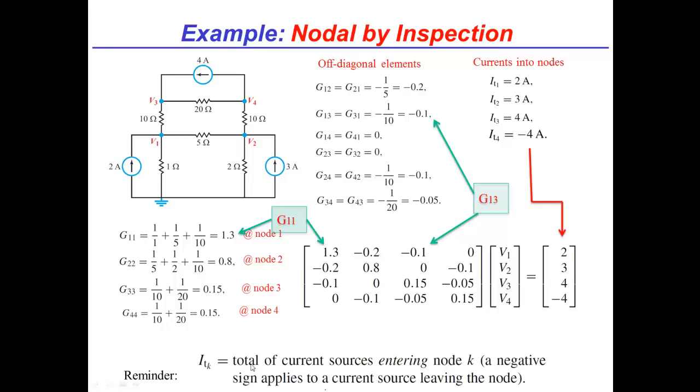All right, so we've now populated the table, and now it's a straight matrix equation, which is relatively easy to solve, either using standard matrix manipulation, or you can plug it into your favorite numerical analysis tool. So the thing to point out is, like you said, you can go solve this now. You're done with these system equations. If you'd done this by nodal, you'd have the same answer. That's right. The equations you would get would have the same answer.